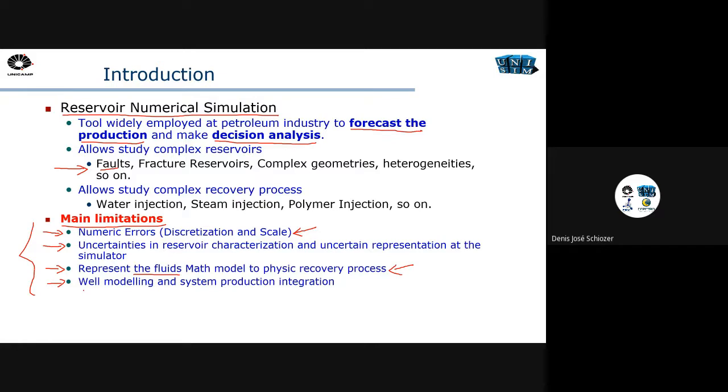Is the well modeling. We are going to see that the well is a very important part of the reservoir simulation models. Why? Because the wells are the place where we are going to measure production and measure the injections and so on. So sometimes we have very good models.